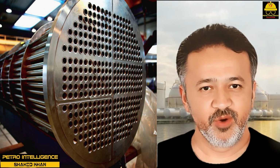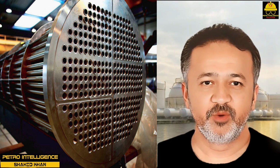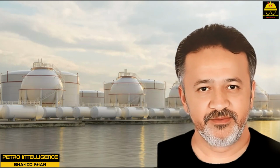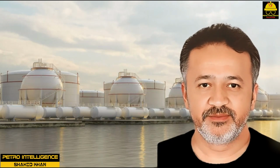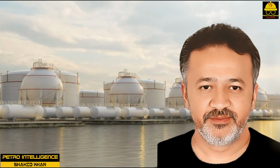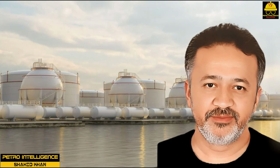Some brasses, notably those containing lead and antimony, have good anti-friction properties and are widely used as bearing materials in pumps and compressors. The bronzes are a second family of copper alloys. These alloys contain 90% or more copper. Aluminum, tin, or silicon makes up the balance.